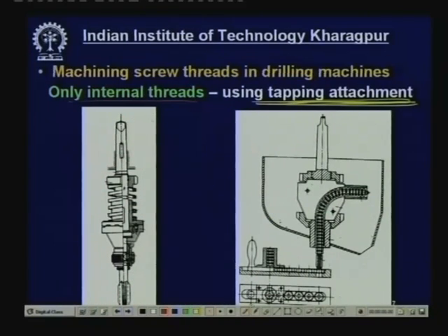One is the part which is fitted into the spindle, and there is a clutch, and this part is separable by the spring, not exactly separable, but a small gap can be created and they are held in position by the spring. Now during return there will be a small gap in between the clutches, and this will take little time to return, and then the spring will bring it back, and there will again be a clutch joint, and they will rotate simultaneously for bringing back.